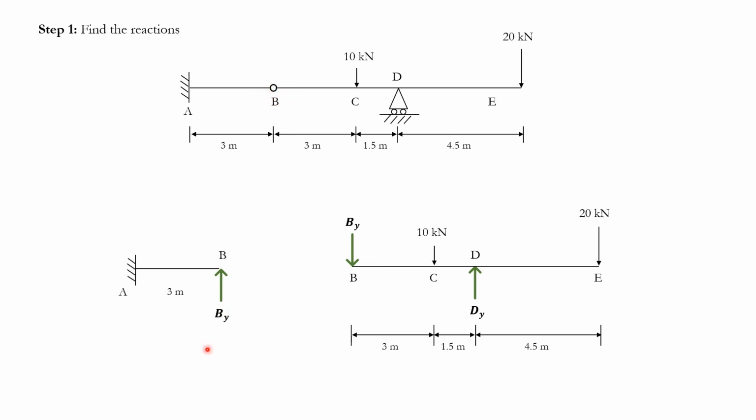And then By, okay, so how do we analyze this one? Free body diagram again. So remove the fixed support there. What are the reactions there? Of course, a moment and a force there. So what we can do is just analyze this one. Where do we start from? Well, as you can imagine, in this one, how many unknowns do I have? 1, 2, 3. Can I solve this? No. But in this one, I have 1 unknown, 2 unknowns. Very similar to the previous question that we did. So we have 2 main equations and 2 unknowns. So we can solve this problem pretty easily.